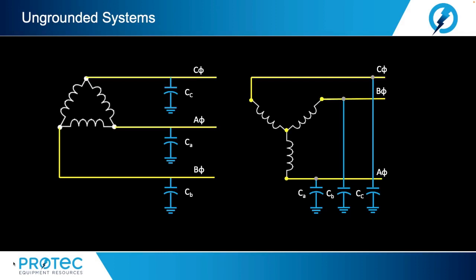Let's start with the ungrounded systems. The ungrounded circuit historically has been selected for those systems where service continuity is of primary concern. An ungrounded system is a system, circuit, or apparatus in which there is no intentional connection between the system conductors and earth. A system may still be considered ungrounded if there is a possible connection to earth ground through potential measuring devices or very high impedance devices.